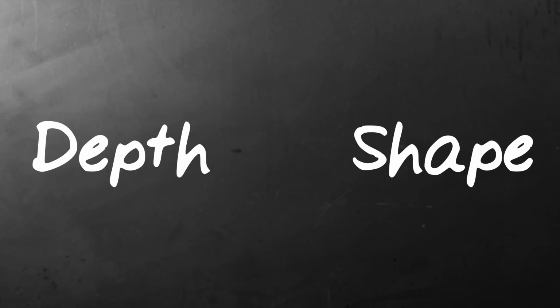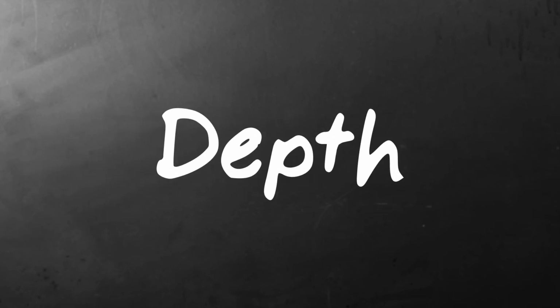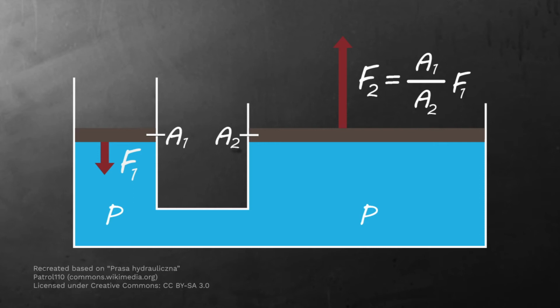So again, the key thing that matters here is depth. The shape doesn't really matter. All that matters is how deep we are. And this allows us to come up with some pretty useful hydraulic levers. Figure 7 is an illustration of a hydrostatic lever. On the left-hand side, we have a small force applied over a small area. On the right-hand side, we have a large force applied over a large area. And the reason those two go up and down together is because the pressure underneath is the same. And the pressure is always a force divided by an area.